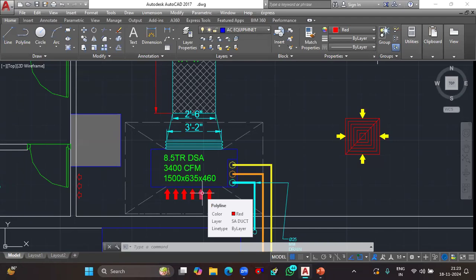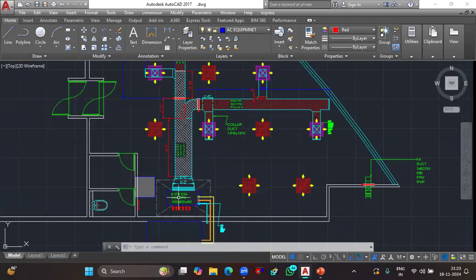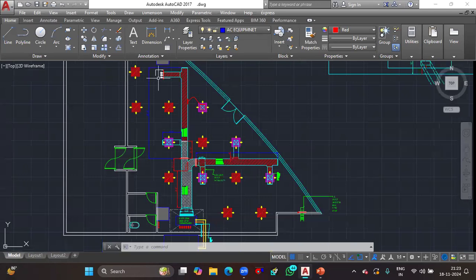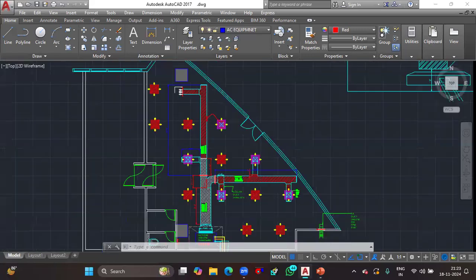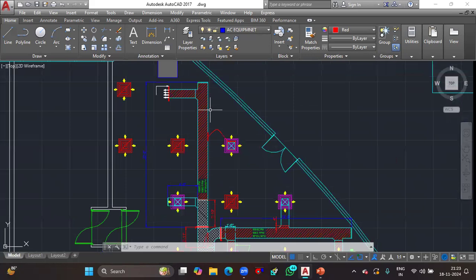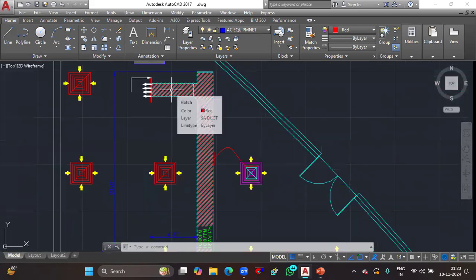So we studied about the drafting of duct, isn't it? We know that air should flow across each and every duct, and it needs to reach even the extreme tail end of the duct itself. So how to ensure that? You can use anemometers on the tail ends of the duct to check whether you have enough amount of air according to the requirement. We need to assure that the air reaches even the tail ends. In order to do this, we need to start with a calculation. That's what is called fan selection.